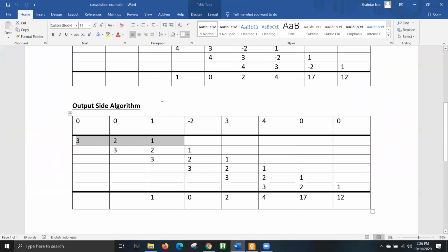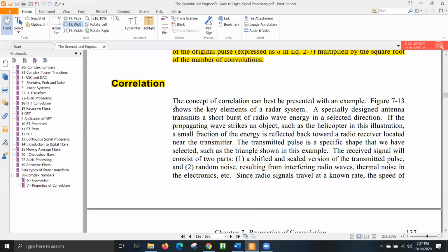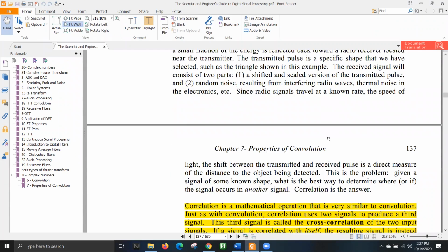This is just like if you send the inverted version of the impulse response through the convolution algorithm, convolution will perform the inversion internally. So the inversion is getting cancelled, and you get 1 to 3 instead of 3 to 1. This is what it basically means. This is what correlation actually does.